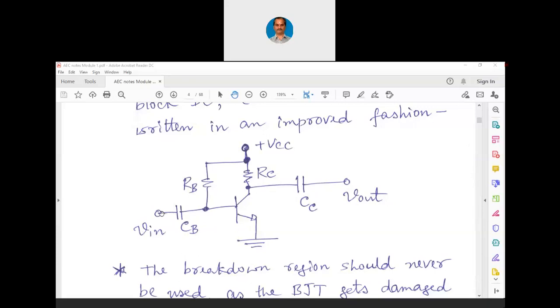That AC signal is going into the laptop now. In the laptop, it is going to be amplified. After that, in the laptop there is one ADC, an analog to digital converter. That ADC will convert my voice into digital, and the digital signal is connected to the microprocessor in the laptop. The microprocessor processes the signal with digital signal processing, and modulates it onto an analog carrier. It is a 2.4 gigahertz carrier wave in the Wi-Fi connection. So through this 2.4 gigahertz radio wave, through the Wi-Fi, it is reaching you. This is what is happening between you and me.